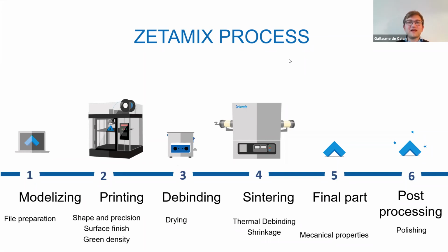We usually feel that if you're careful, you can remove support without any problem. But of course, you need to be careful not to make any shock on the part, or you will initiate some cracks. Again, if the supports are relatively simple, if all of them come from the plate, the alternative way is to do it either in a soluble material or even in PLA, and to use the process to remove it. But you don't remove it manually, and so you remove that risk.